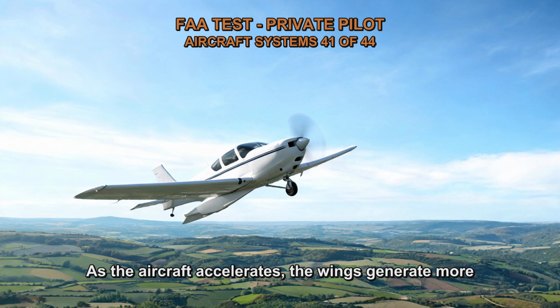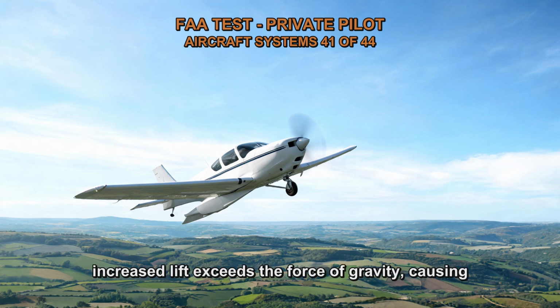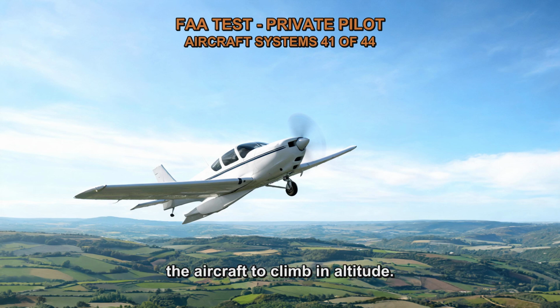As the aircraft accelerates, the wings generate more lift due to the increased airflow over the airfoil surfaces. The combination of the upward thrust and the increased lift exceeds the force of gravity, causing the aircraft to climb in altitude. During the climb, the pilot can control the aircraft's pitch angle and rate of climb by adjusting the elevator control surfaces. By increasing the pitch angle, the pilot can further enhance the climb rate and altitude gain.